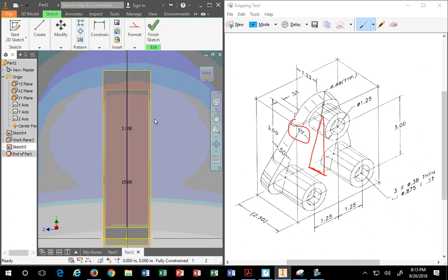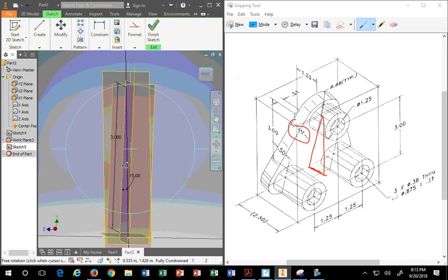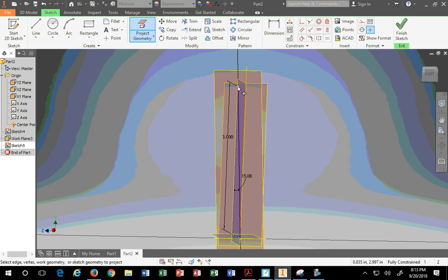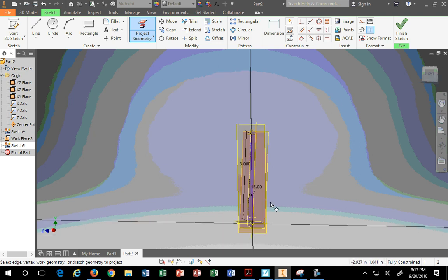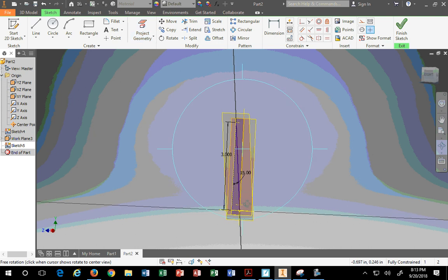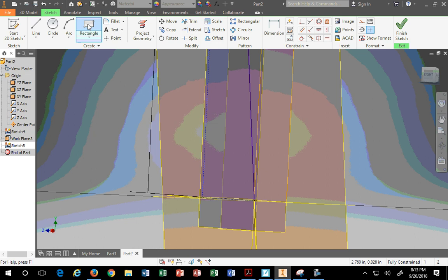So now we're looking at this plane head on. We have a line that we could use for reference off of my parent plane right here. We have this backbone that we can use here. We have a spot right up there. So I do recommend doing a little project geometry of the dots that represent where my positions are. You'll notice that that back dot went in the wrong spot. I don't want to build anything up there, so that item I delete. This guy's good, but this bottom one, I actually want it right there. So I'm going to project geometry of that up. See how it bounced all the way back there again. So if I do it off the back object, I should get the same result. Let's find out.